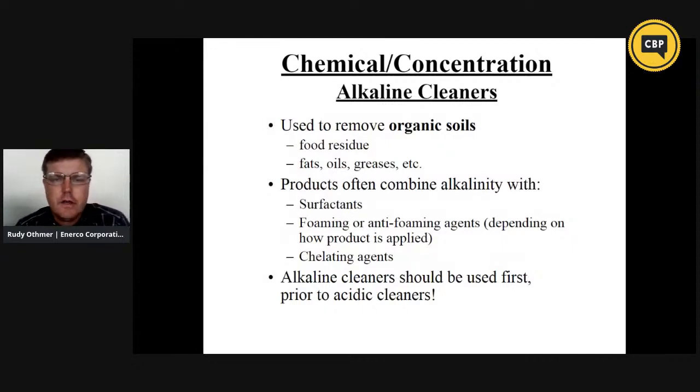Our alkaline cleaners, in general, are used for removal of organic soils. So we're thinking about our oils, residue from the hops, so on and so forth. All the things that were once living that are now hanging out inside of our tank and that we need to remove, we do so with an alkaline cleaner.